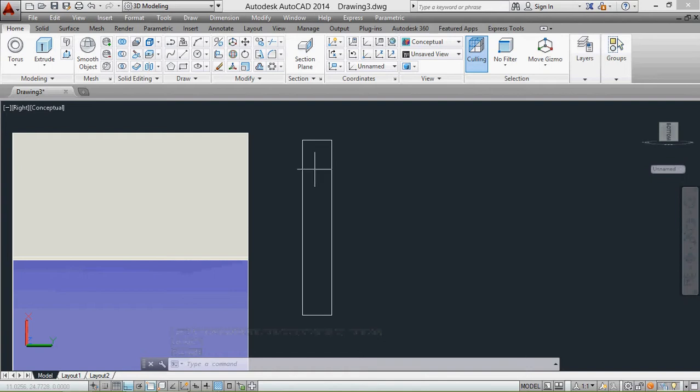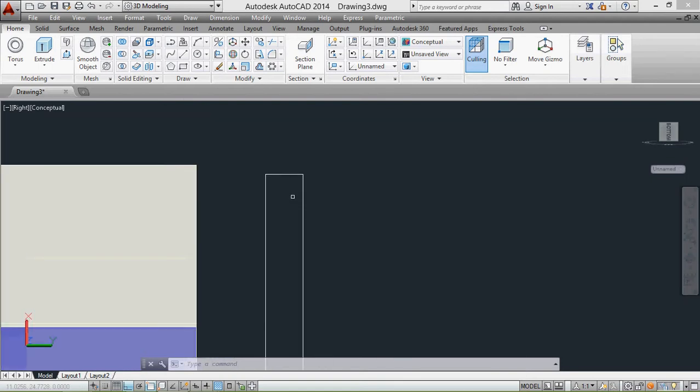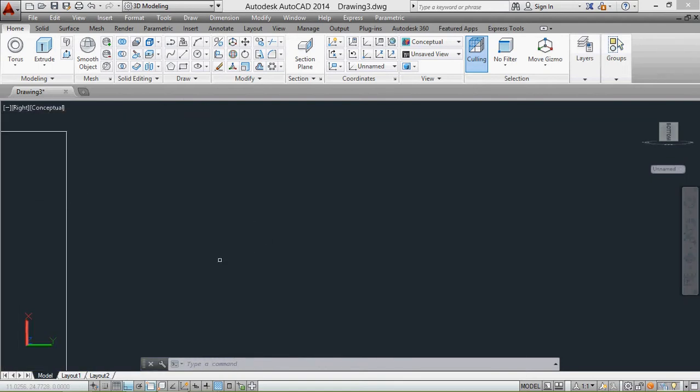We need to create those slots for the screws. So we're going to design keyhole slots, or sort of like that, with a bottom diameter of 0.285 and a top diameter of 0.175 and a height of 1.5. To do that, you can do it in the rectangle or next to it and then just move it to position. It's up to you.